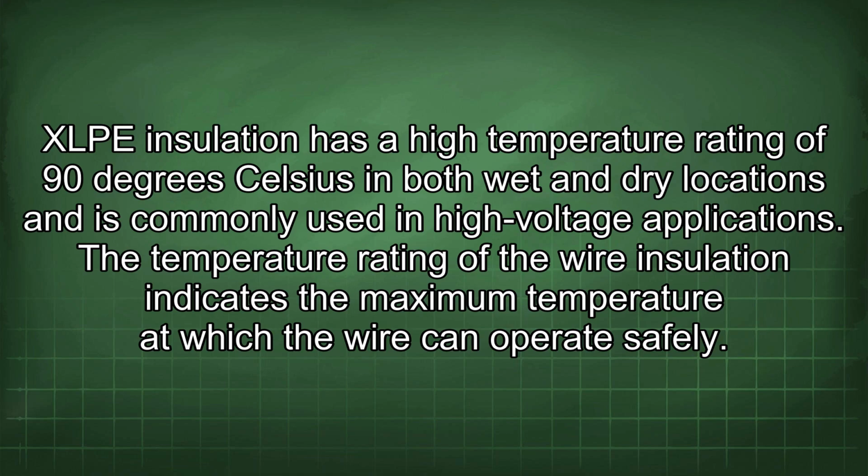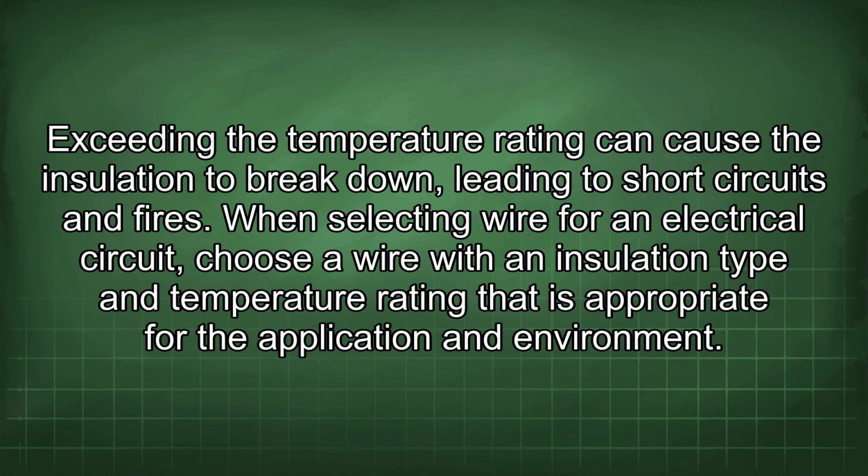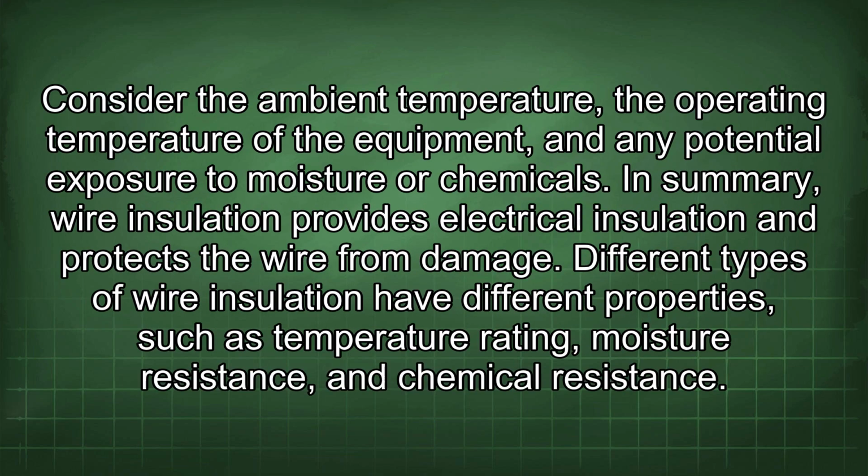The temperature rating of the wire insulation indicates the maximum temperature at which the wire can operate safely. Exceeding the temperature rating can cause the insulation to break down, leading to short circuits and fires. When selecting wire for an electrical circuit, choose a wire with an insulation type and temperature rating that is appropriate for the application and environment. Consider the ambient temperature, the operating temperature of the equipment, and any potential exposure to moisture or chemicals.